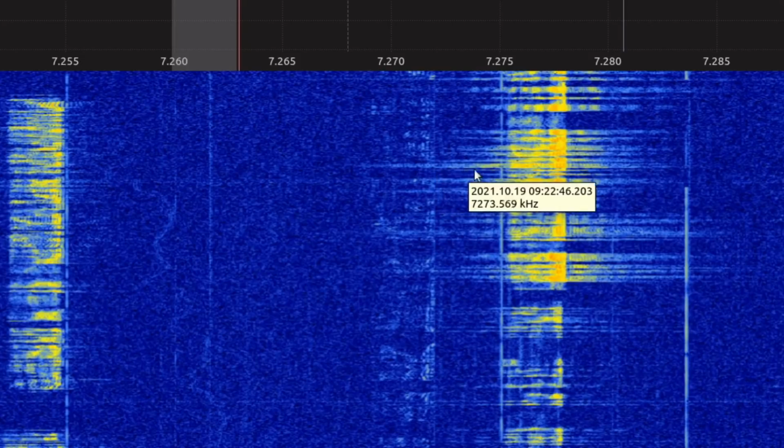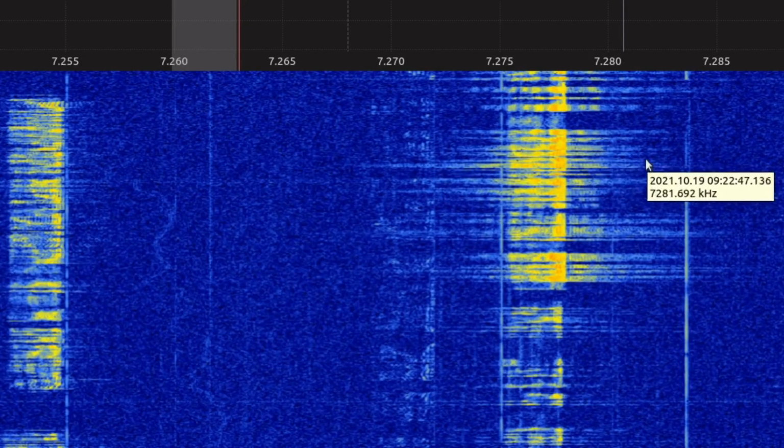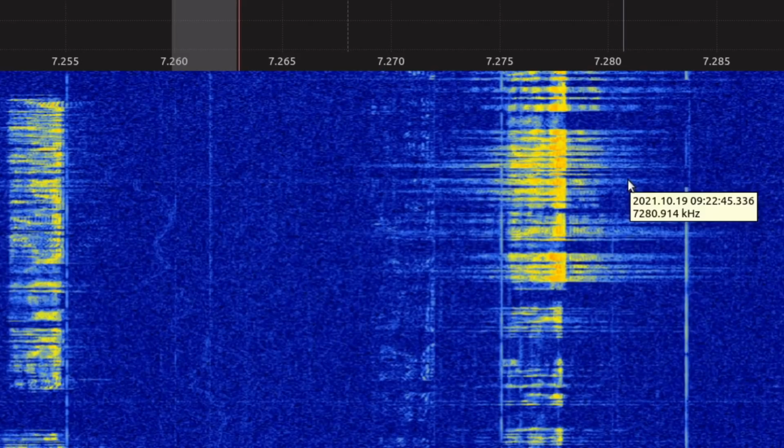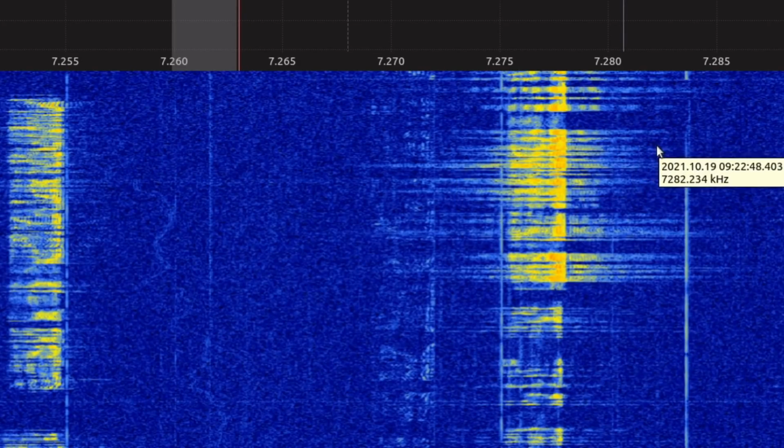He's occupying 10 kilohertz of spectrum space where he should only be occupying 3. So that's why splatter is bad. It'll interfere with stations. It'll cause you to make unusable more of a chunk of spectrum than you should be occupying. It's just inconsiderate. It's not good. Plus, it degrades the quality of your voice.